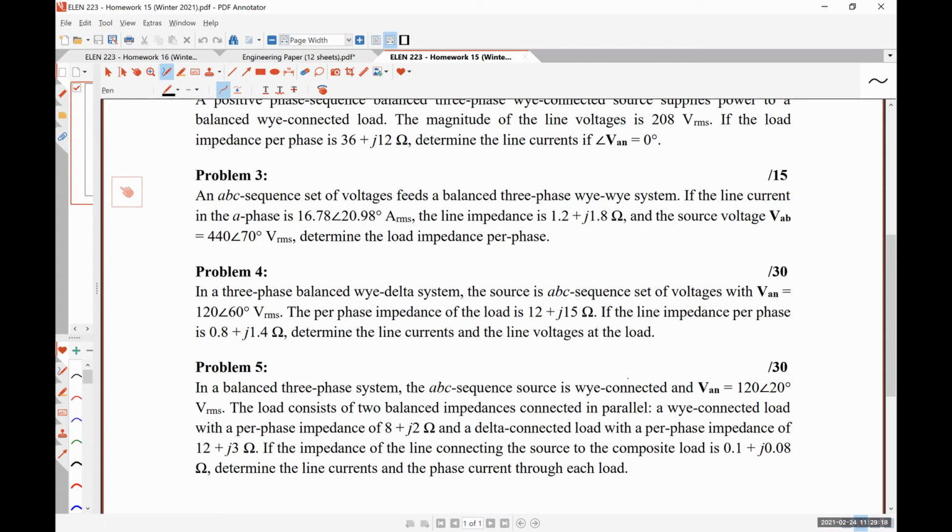Well, it all depends on what kind of loads you have. Most of the work that I do is lighting systems and then HVAC systems, which might be 3-phase or might be 1-phase or some combination thereof. The compressor might be a 3-phase motor, but the blower fan might be single-phase, and you can actually go inside of it and rewire which phases it's connected to. It's got a transformer inside the HVAC unit that's easily accessible so that you can do things like that.